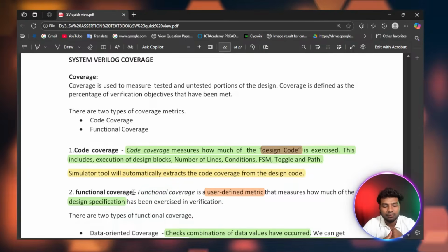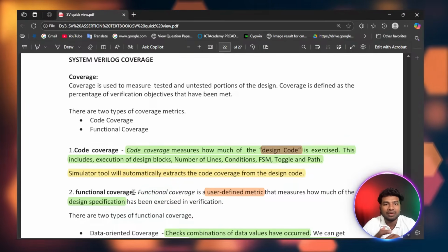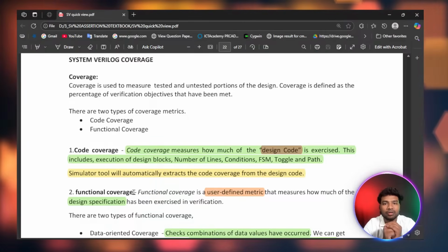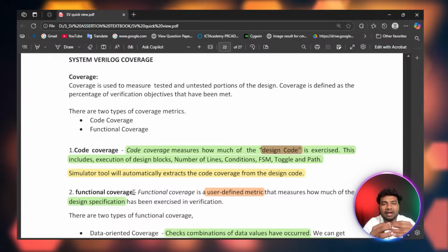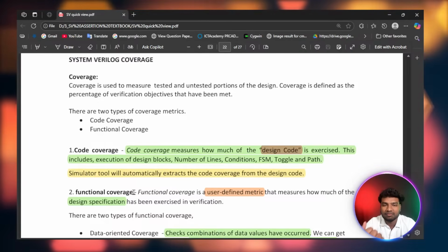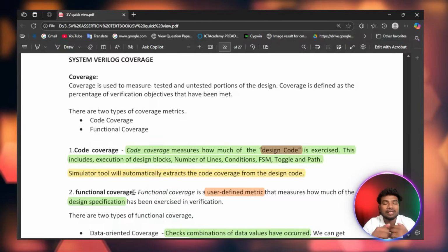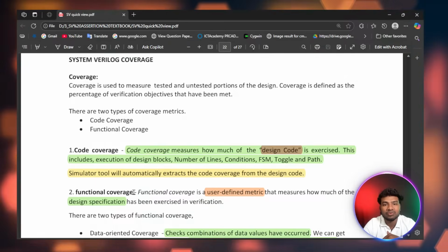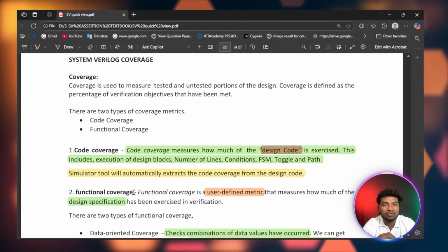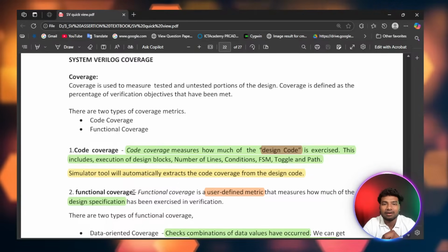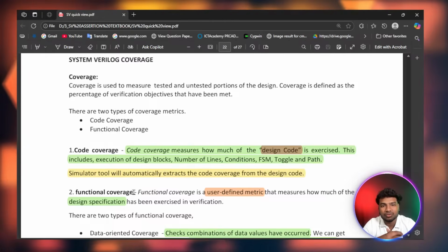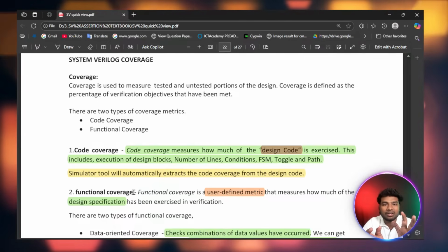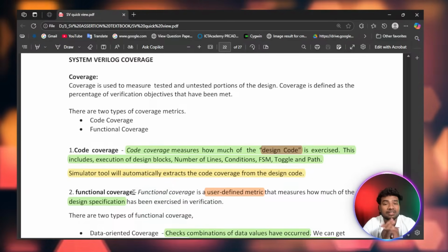Now why is coverage important? We have to check, while doing randomization, whether it is covered or not. For example, you are randomizing one signal between 5 to 25. So literally there are 20 values we have to randomize. Our work is to check whether those 20 values are randomized, that is, whether the values are hit. If they are hit, our randomization works fine and there are no issues. If some values like 5, 7, 20, 21 are not hit, then any miss in randomization is an error.